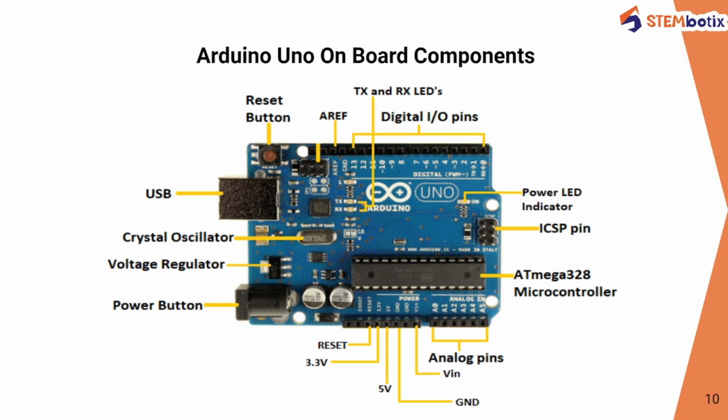After that, we have the ICSP pin. This is an ICSP pin, meaning in-circuit serial programming pin, which allows the user to program the firmware of the Arduino Uno board. These are the header pins of MOSI, MISO, SCK, reset, VCC and ground. It is often referred to as SPI, serial peripheral interface, which could be considered as an expansion of the output.